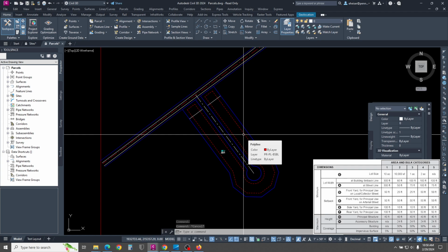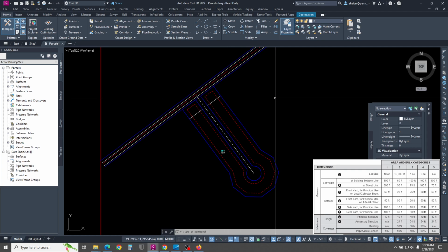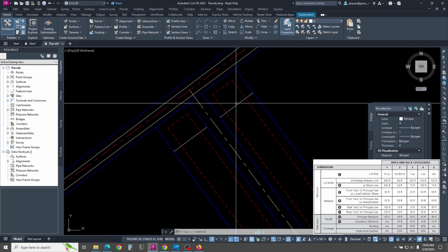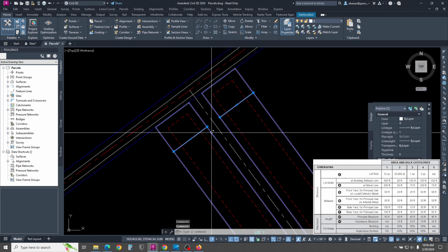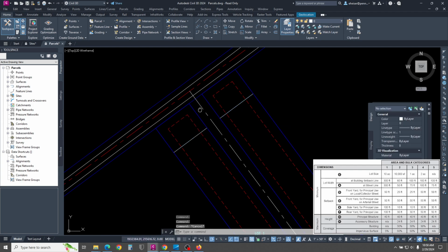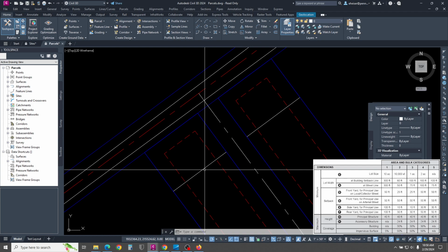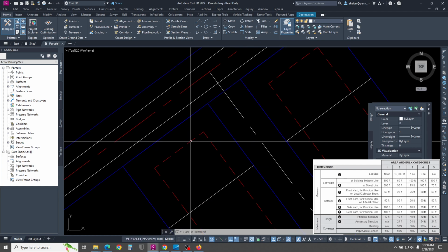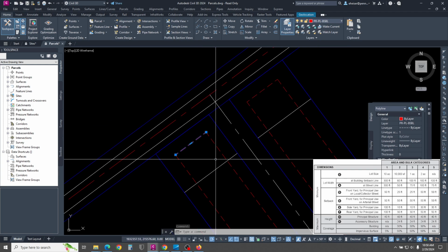The next step I would do is create the corner lots manually, because you have to account for having 2 front setbacks. So I already went in and put dummy lines in here, kind of construction lines, and I just put them on the 0 layer for now. But we're going to use these to set our corner lots. And essentially all I did was took the minimum lot width and I added the extra 15 feet to go from the front setback to the side setback distance.